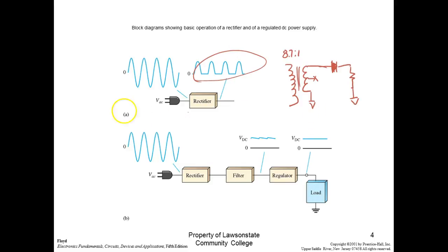So people call this ground all the time. This is the symbol for a ground: three lines, going smaller and smaller, not four, not two, three lines. But you see it's misused all the time. They'll say your negative lead is supposed to be connected to ground, but it's not connected to ground, it's connected to the chassis of your car. So the chassis of your car is a common, right? This cell phone doesn't have a ground. It's got a common, right? You need to understand the two. Even though it's a misused term, and calling it ground is not going to be a big deal, you need to understand the difference between a common and a ground.